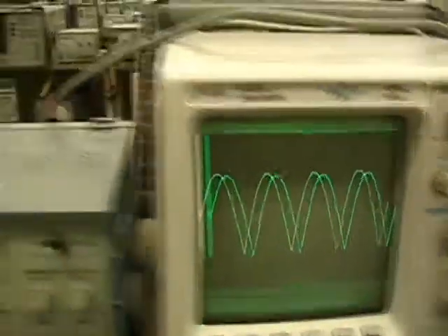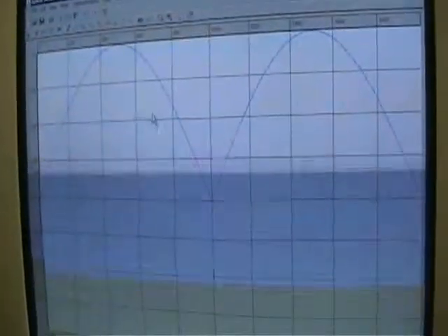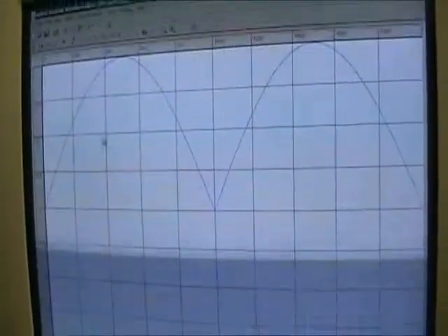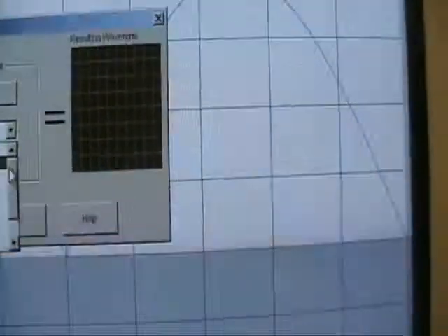Now, cooler than that, we can also create something like a half wave rectified signal. How do we get a half wave rectified signal from the full wave? Well, if we simply add a regular sine wave, which is going positive and negative, to this waveform, that will do it. So go up to the math function, addition, and we will simply add a sine wave, which is selected directly.